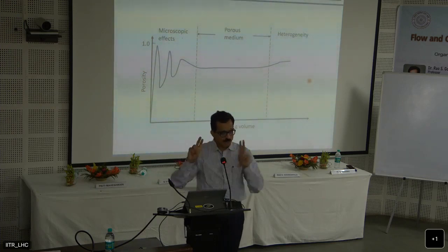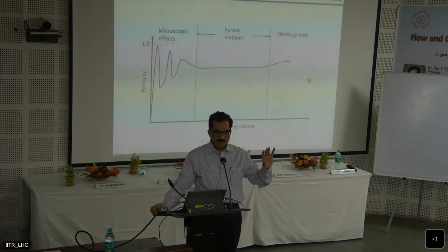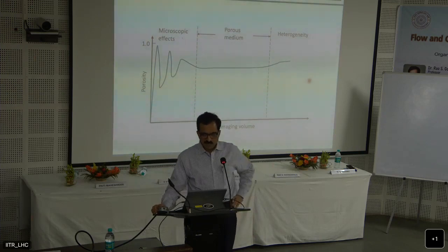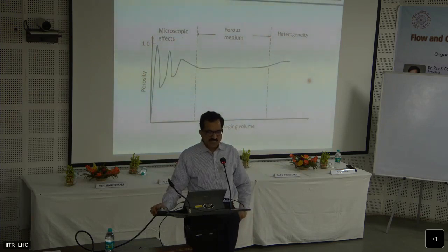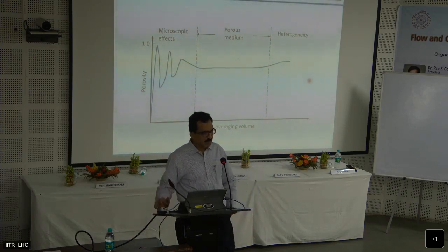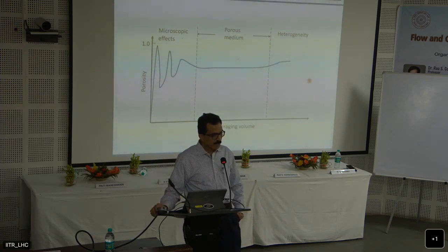I'm not sure it's easy, but one way is that you can determine the total porosity, and then you do an experiment with a tracer which does not react with the porous media. That may not be an easy experiment, but it is an easier experiment that will determine the effective porosity, because the average velocity will be reflective of the effective porosity of the medium. Direct measurements, I'm struggling to think of.